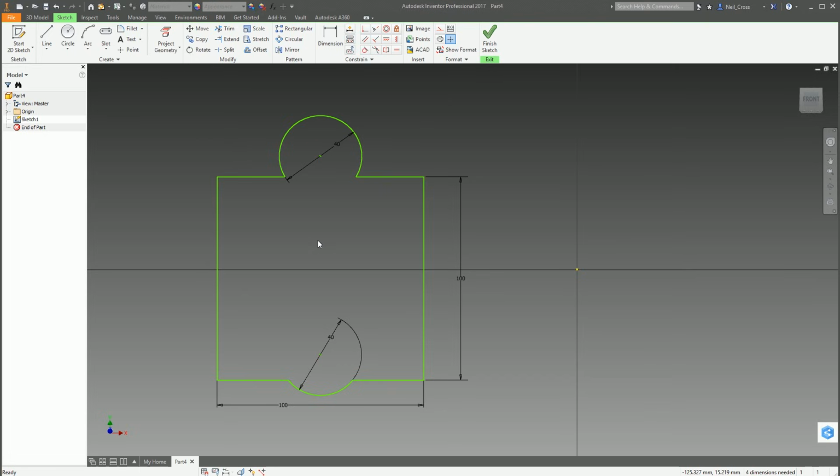And then from that point onwards, you might find you get to a point where you've got no more room for 2D constraints. You've placed as many 2D constraints as you need to. The only thing left now is to place some dimensions on to get the sizes right. That might be what's left to do. But in this case, there's not. There's a few more that we can place.